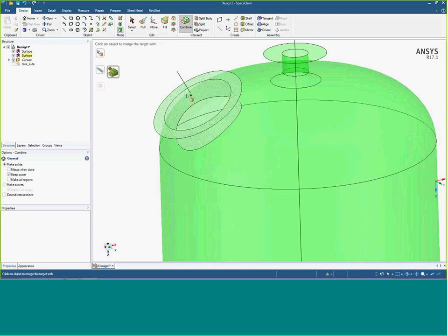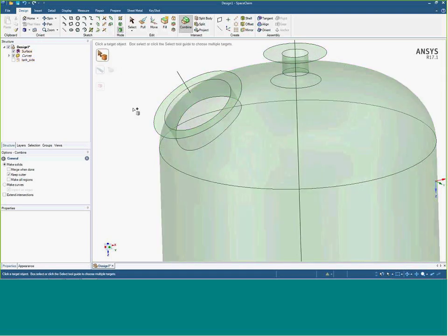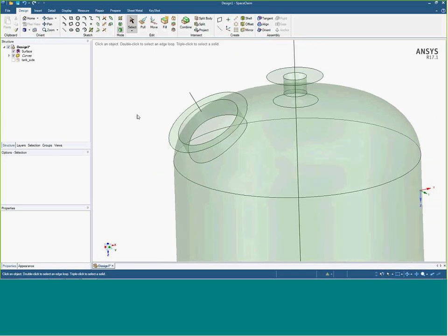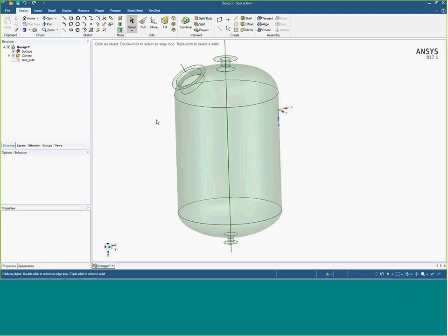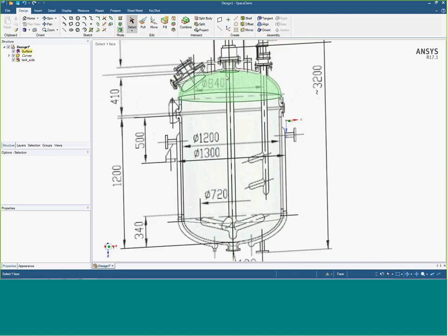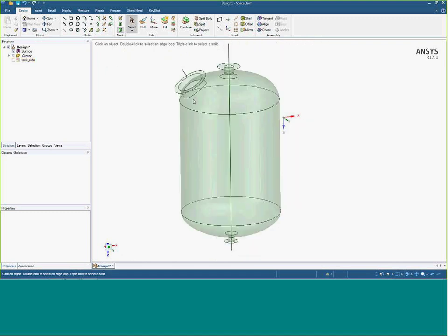So now, click this body, and then those two surfaces got added together. So we can either add or split with combine. So that's good. Now we have, let's just say we're good enough with creating our surface. It's pretty close to the tank geometry here, minus some other ports. Let's turn this into a solid.